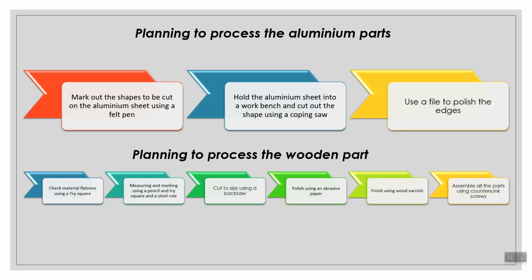I will cut the piece of wood to size using a back saw. I will polish using an abrasive paper. I will finish the product using wood varnish. And I will assemble all the parts using countersunk screws. So this is my plan for making the base and assembly.